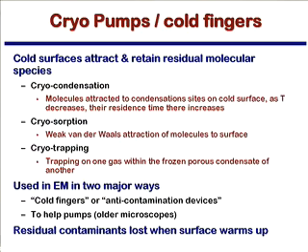I like them. They're kind of a pain in the neck, but they do help a little bit. And the real reason for this is that once you're at 10 to the minus 6 torr or whatever, you don't have to worry much about your electrons scattering off gases in the column. You're really now more worried about contamination on your sample, extra stuff that came in with your sample, like your finger grease, which is usually what it is. If your electron beam's coming in, it causes some of that extra contamination to get put up into the vacuum off of the surface. Then instead of going back down where you're looking, it may go over to this cold finger. So that's what it's primarily being used for, to take care of additional contamination.